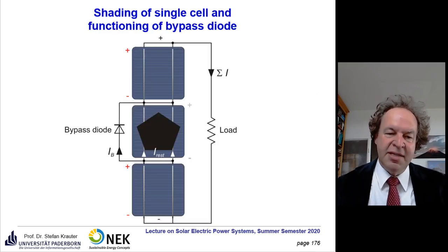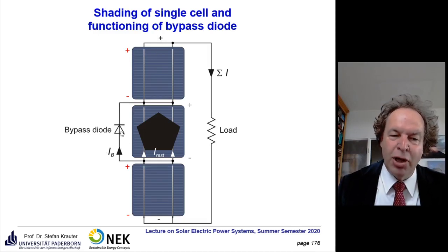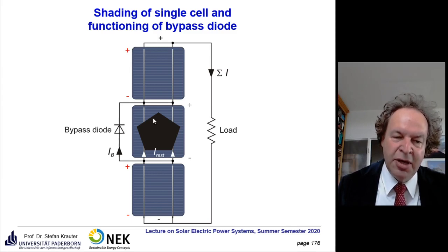What you can do against it, you saw it already in that picture. This is a so-called bypass diode. So you put a diode here, so-called anti-parallel, not in parallel, but with a different direction. So the diode is looking in that direction. Here you have the cathode, and here you have the anode. The cell within the solar cell is vice versa here.